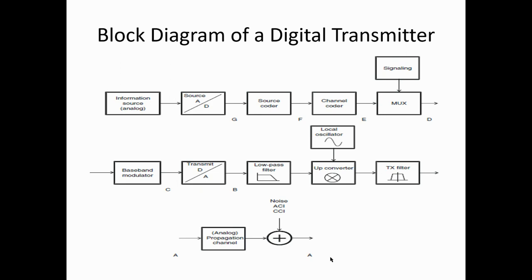And then we have a modulator. The modulator normally does the process of assigning data bits to symbols. We have data bits of zeros and ones, and for zeros and ones it has to be mapped to the corresponding symbols. That process is called modulation. Modulation also converts a lower frequency signal to a higher frequency signal by multiplying with the carrier.